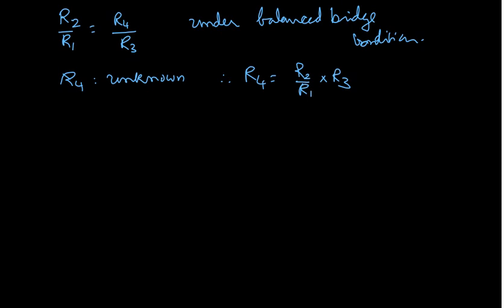I am reading on page 120. Considering the mesh BADB, it is a loop we are considering. That means we have to look at the voltages. 100 into I1, because through that 100 ohms we are sending I1. We assume that I1 is going. 100 into I1, and the galvanometer resistance is also given, therefore that resistance, which is 15 ohms, multiplied by Ig. Minus 60 I2. Why did he put minus? Because that loop direction is opposite to that of I2.